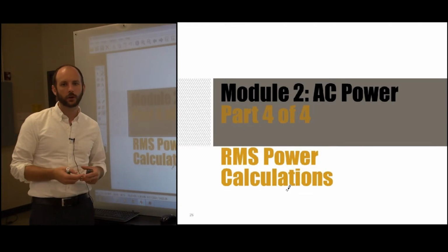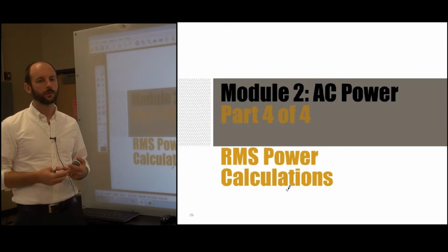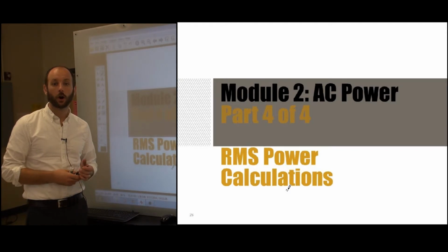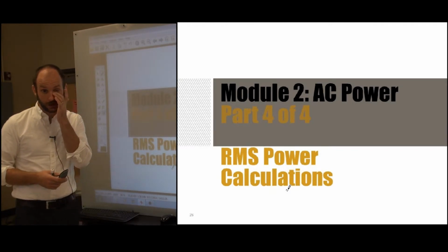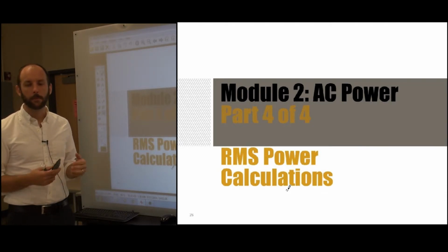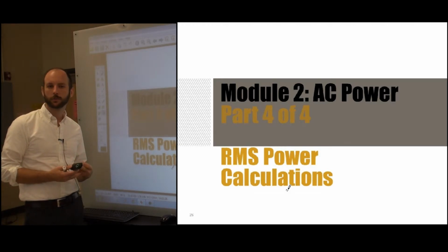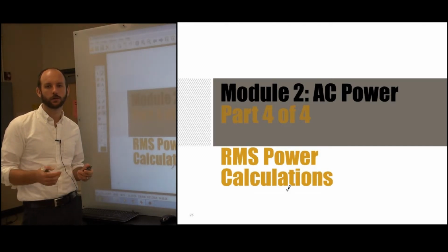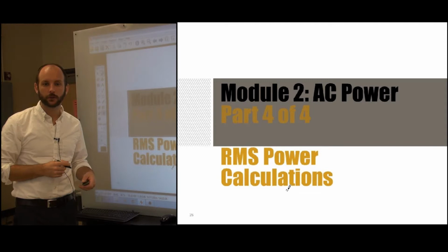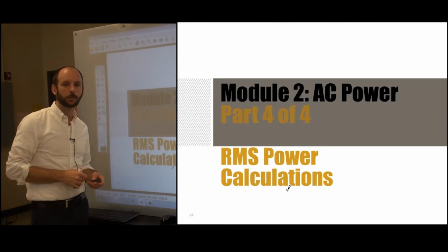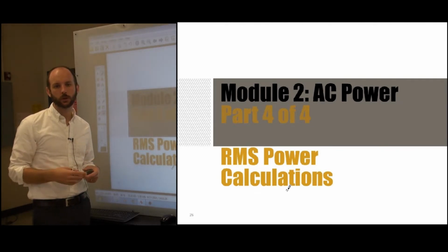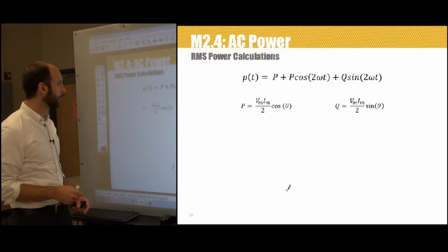In other disciplines, like we said earlier, the peak phasor is often used in ECET. In power, recall that I mentioned that the RMS phasor is typically more useful. In fact, the use of that RMS phasor is so common that most of the time power engineers are simply assuming that voltages and currents have been stated in terms of their RMS values. And so will we in this class. So for the rest of the semester, unless otherwise explicitly stated, we're going to be performing our circuit analysis using the RMS values of voltages and currents. And now we're going to take some time to look at the use of the RMS value for power calculations.